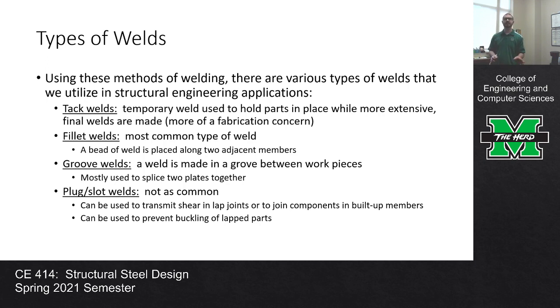So the idea is, okay, I have this weld that I'm going to place. I'm going to join piece A to piece B. So what I'll do is I'll get the piece sort of where I want it. I'll clamp it down, and I'll hit it with a weld real quick, just a little quick, 1 second deposit, and then done. The purpose is just to sort of get it in place, so tack it in place. That's why we call it a tack weld.